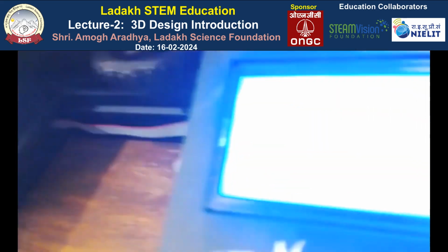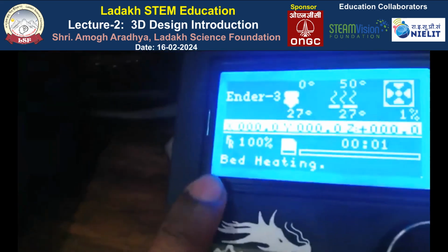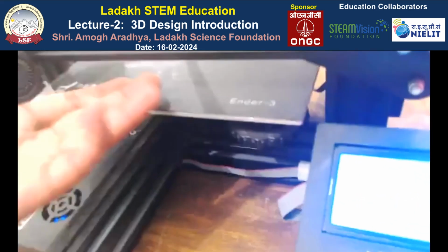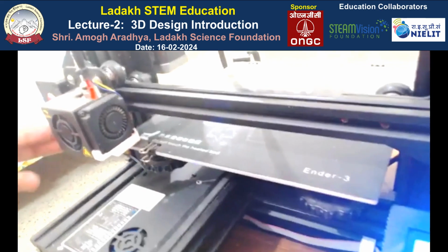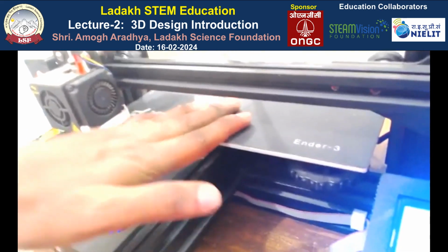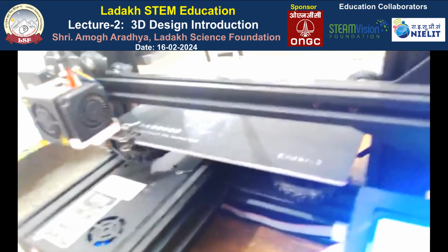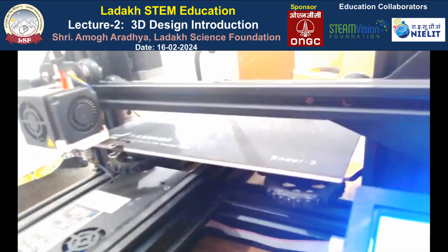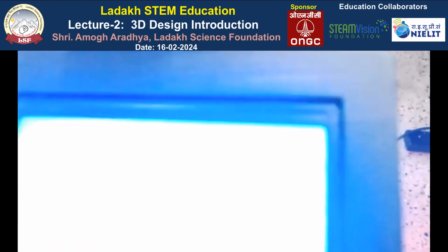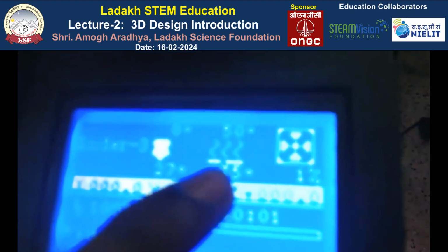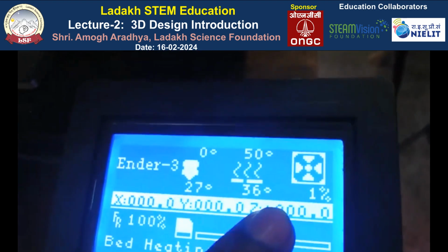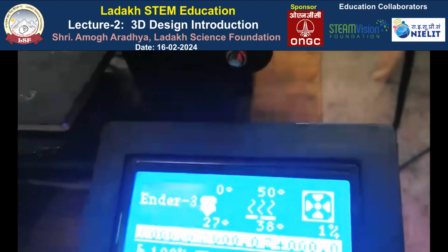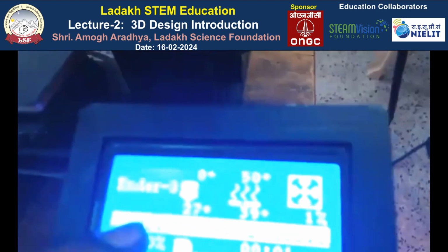print a part. Now you can see that the bed is heating. Bed heating is required for the addition of the material onto this plate, or else the material will come out in between the print and the 3D model will be spoiled. So now you can see that it's slowly heating up. It's going from 36 degrees to 50 degrees, which will take around 3 to 4 minutes.